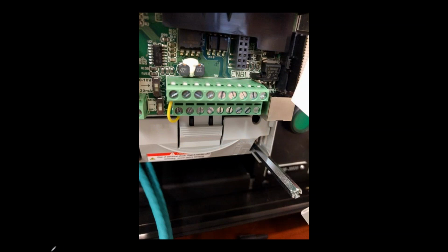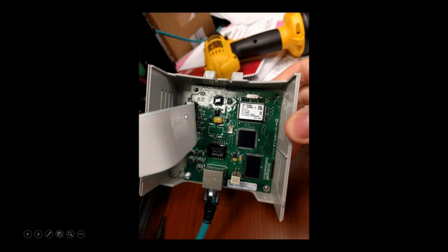Okay, so if I then look at the card that I just pulled off, this is what it looks like. You see a ribbon cable connected to the VFD's card. But here is my Ethernet connection. It's going through here, not to the VFD. So I have to communicate first through this Ethernet card to the VFD, and this translates signals to the VFD. If I'm setting it up, I need to take this off because this computer chip contains everything I need to know to help set things up.